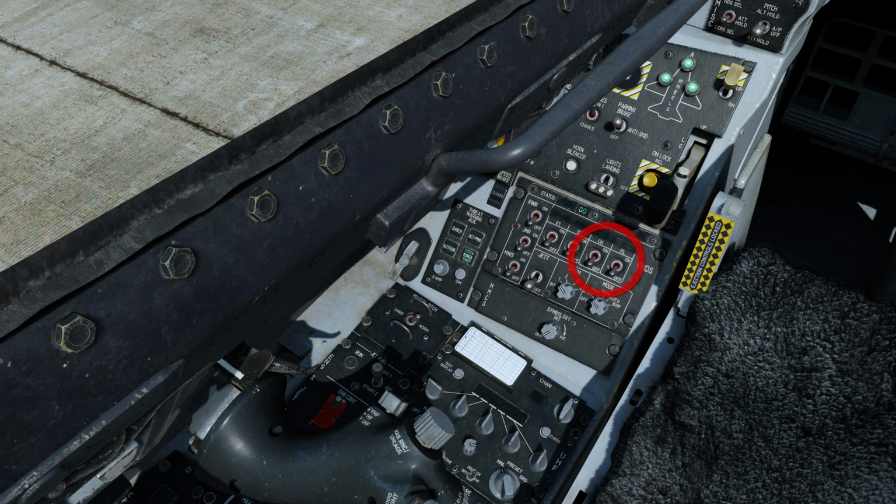4 categories of expendables are listed, though only chaff and flares are implemented. In the on position, the indicator displays the number of expendables remaining. Bingo level is set through the DTC or UFC. When bingo is reached, low is displayed with the number remaining. The indicator remains blank in the off position.